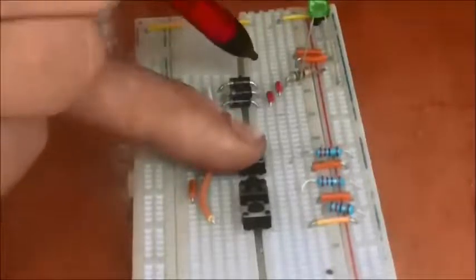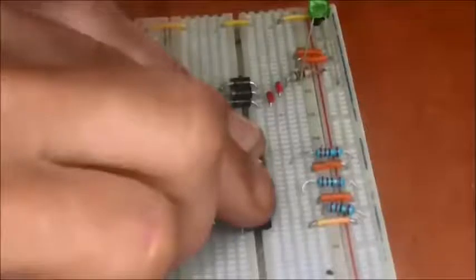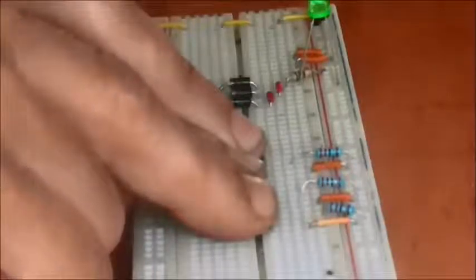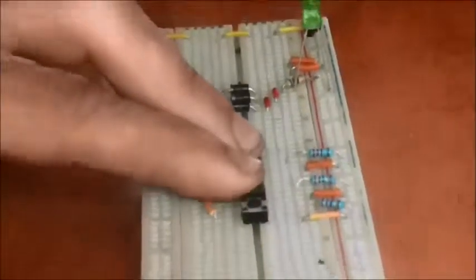As I press the switch, what happens is a 5 volt potential appears there and a 5 volt potential appears there. Now that can't conduct to ground anymore, in fact it can't conduct anywhere, but these 2 still can. And if I press these 2 switches, that one and that one cannot conduct to ground anymore, but this one still can. However, if I press the 3rd switch, none of the diodes can conduct to ground anymore. A voltage is developed that goes across the LED instead. And there it is.